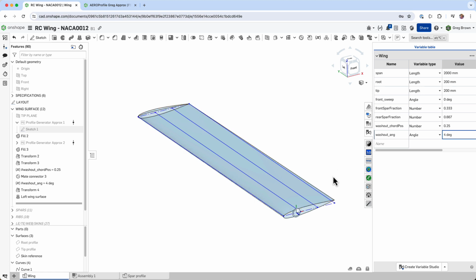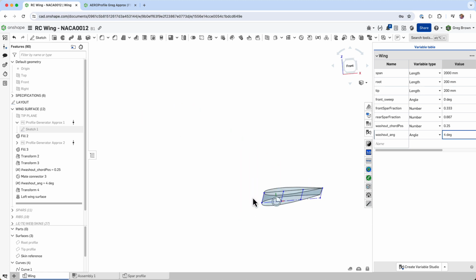You don't want that to happen because you've got control surfaces out here, so you want to keep the flow unstalled or pre-stall when you've got control surfaces out here. It's just a little bit of stability there. So this is structural washout because it's actually happening in the structure.